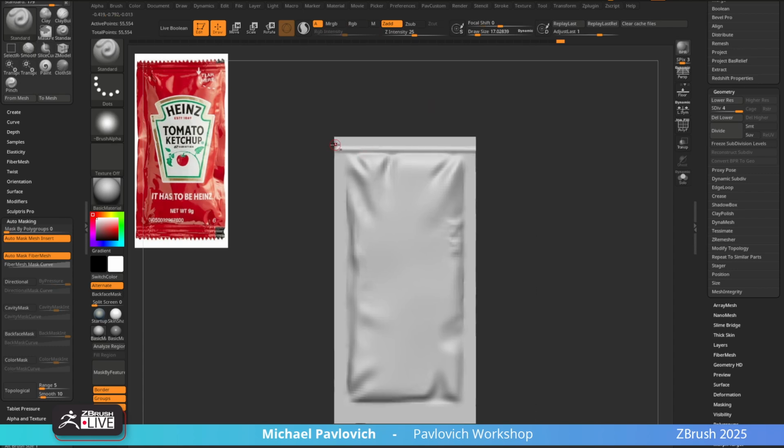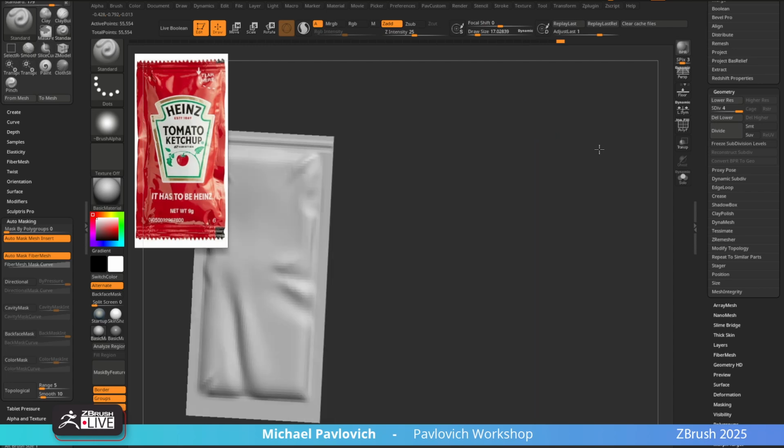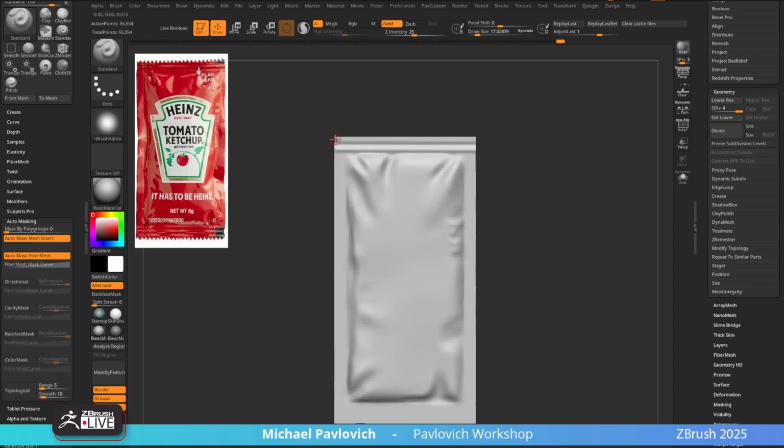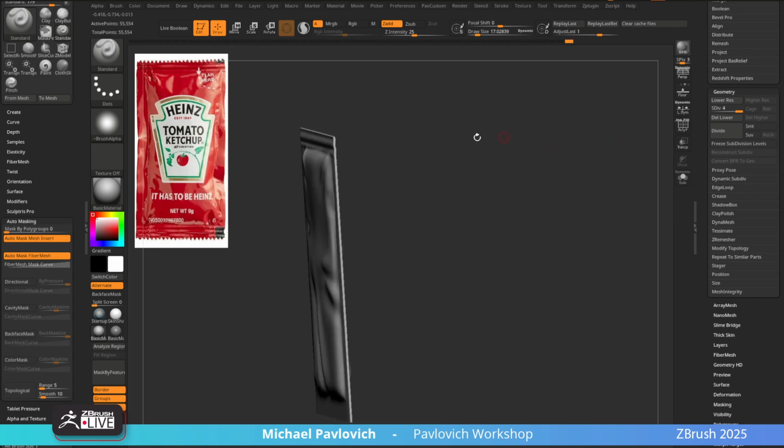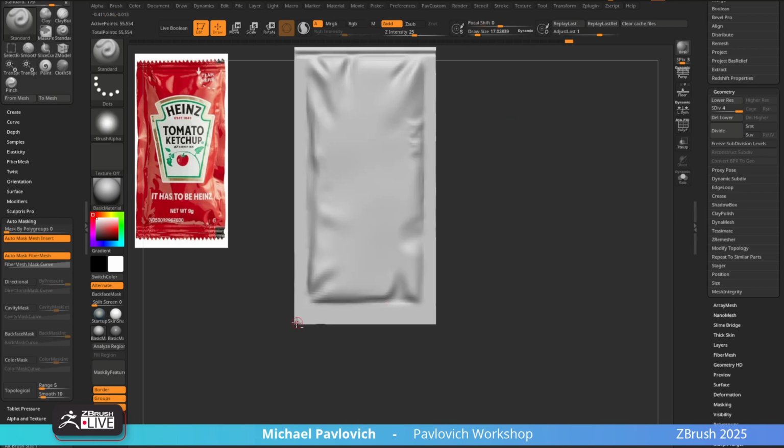And then just above this, I'm going to hold down Shift before I start sculpting, and then hold down Alt. It'll actually punch back through, and that'll punch on the other side. So we can actually just alternate that. And we'll do one more punch through like this. So now we've got that top part wrinkles, and then same thing for the bottom.